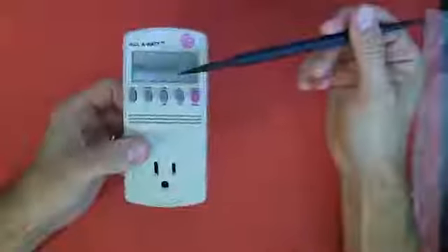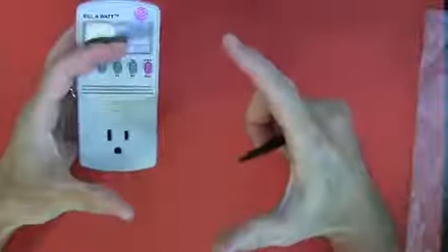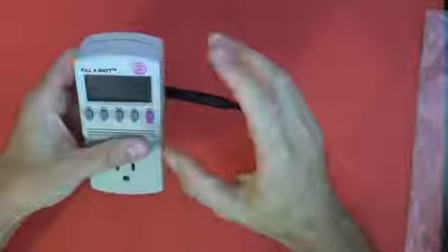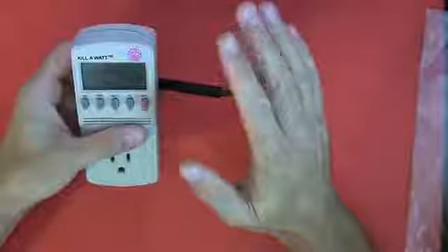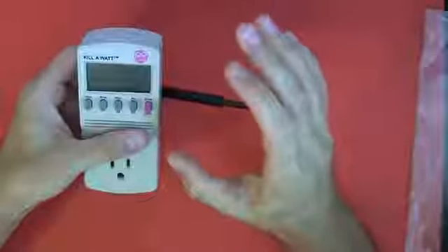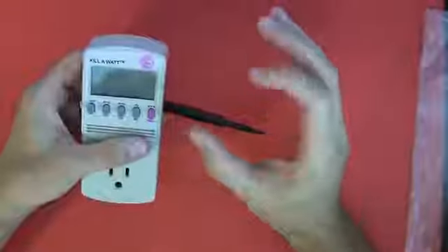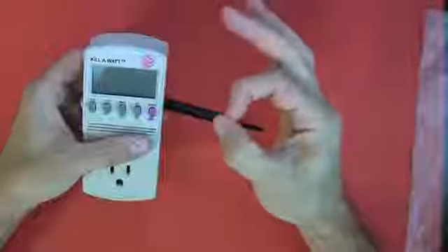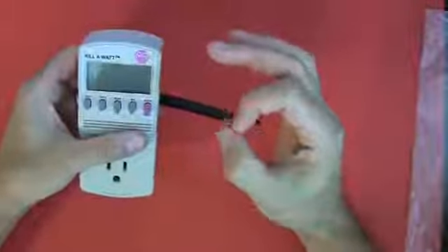So what you can do there, and again, that video I told you about, you can buy the cheaper devices like an OWL or an Efergy. There's quite a few of them now. And those you need to actually clamp around the individual circuits in your DB board. So that gets a bit more tricky because you need to know what you're doing. You need to be qualified. I certainly don't recommend that you open up your DB board unless you know what you're doing, because it's very dangerous. But a qualified person who would potentially come and do an audit on your house could put these current clamps or current taps around the individual circuits to measure what each of them is actually using.